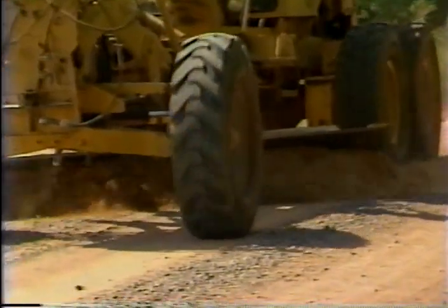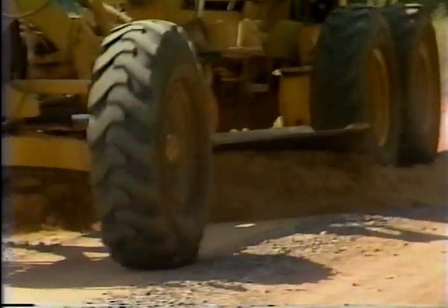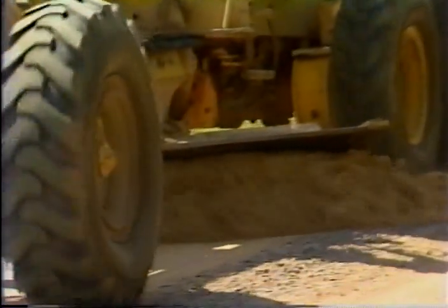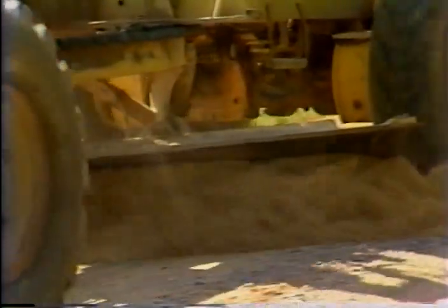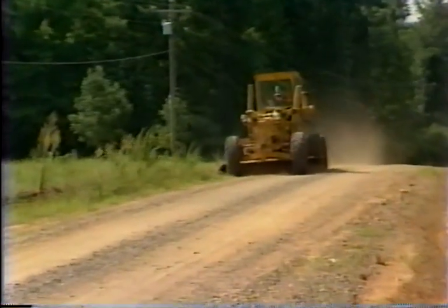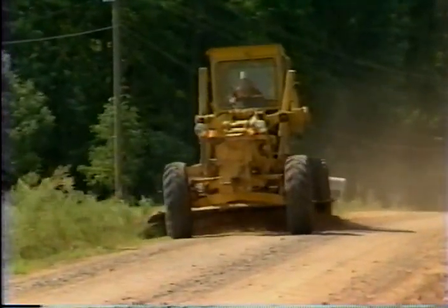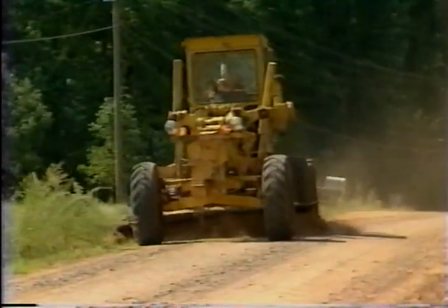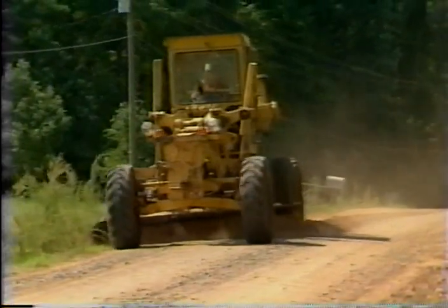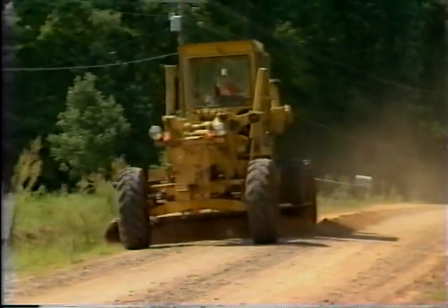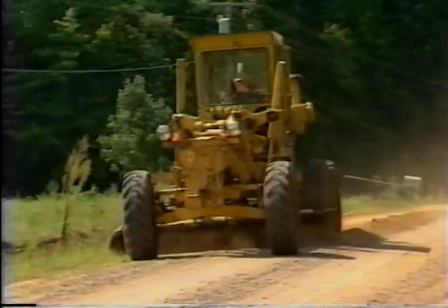Do not put enough downward pressure on the blade to cause the blade to cut into the crust of the roadway. Proceed at a slow, steady speed, generally 3 to 5 miles per hour. Speeds faster than this may cause the blade to bounce and create an unevenness in the surface of the roadway.